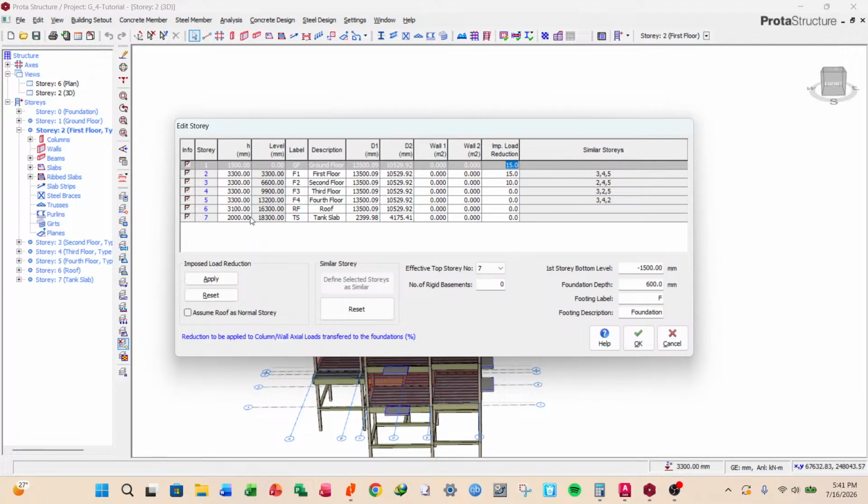Okay, and that is all. Then we had proposed to change the story height for the tank slab level to increase it to 2,500. And we were giving headroom reasons, but when you study the architecture drawings very well, you come to note that actually that area is not accessible, and it actually has no door to the roof level. Okay, so the roof is not accessible at all.